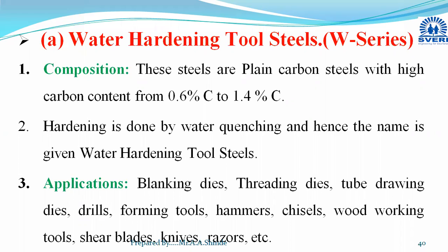Like this, oxidation will occur, and sometimes grain coarsening will occur at higher temperature ranges. Hence we cannot use them for any heat treatment process or for higher temperature applications.